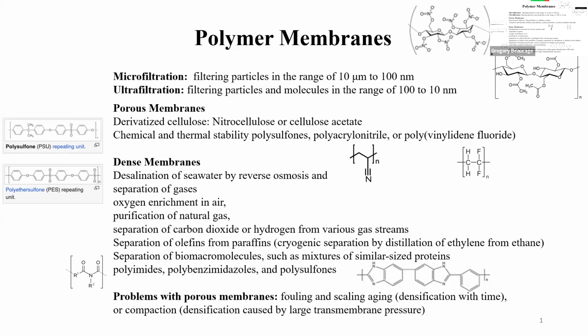In the environmental field for wastewater treatment, the back flushing routine is pretty typical. In industrial microfiltration, replacing the filter is more typical, right? Depending on what you're doing and how expensive your filters are, you might choose one of those two ways. So clogging of the filters is one problem, and rupturing of the filter is the other problem.